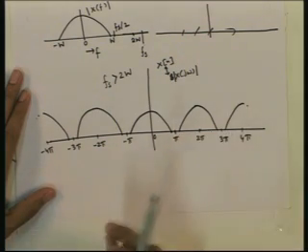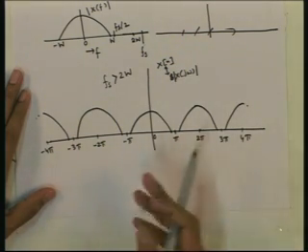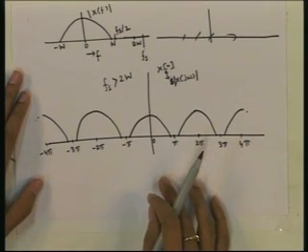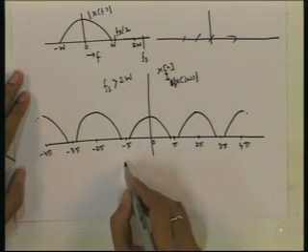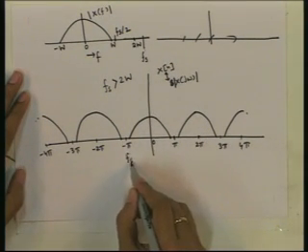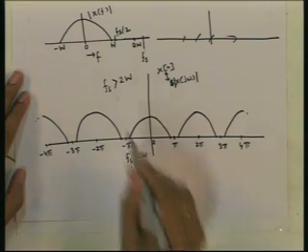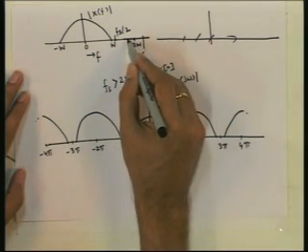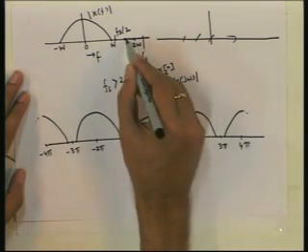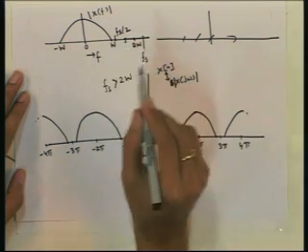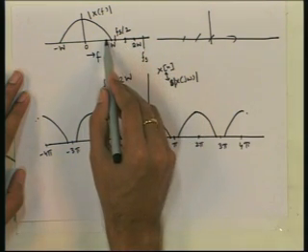There is no mix up, what is called the aliasing, there is no aliasing. Now, let us see what will happen if Fs is less than 2W, that is Fs is somewhere here and Fs by 2 will be somewhere here, less than W.